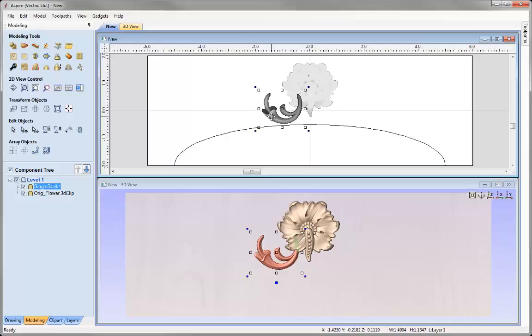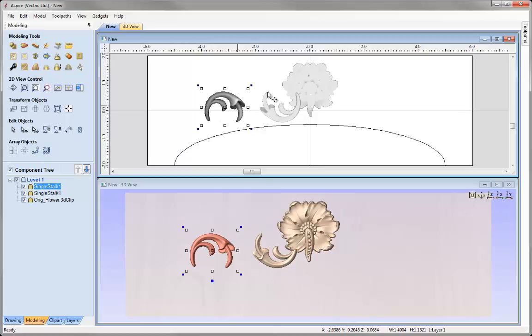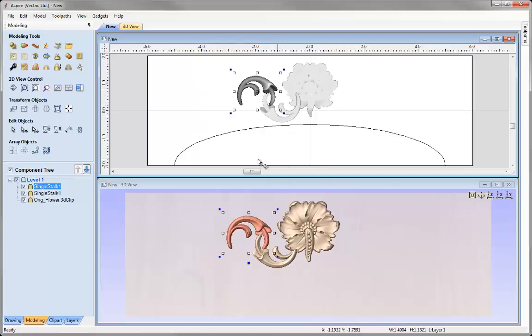Again, if we take that now, let's just jog that up and over a little bit with the arrow keys, shift and control to copy that across, and then H and V on the keyboard to mirror it, and then I'm just going to position that here. So doing a mirror like this and positioning it in an opposite way creates this nice symmetry. They're the same size parts, we've got the symmetry of these leaves and the flow of this going around.